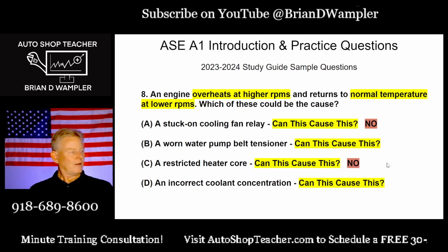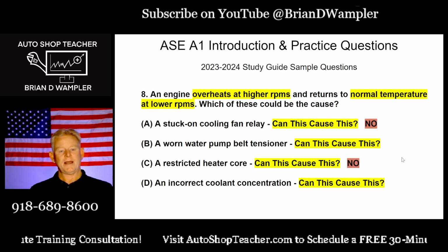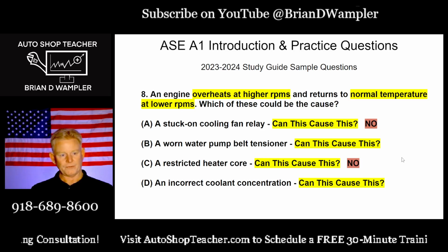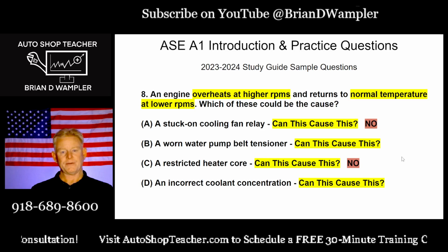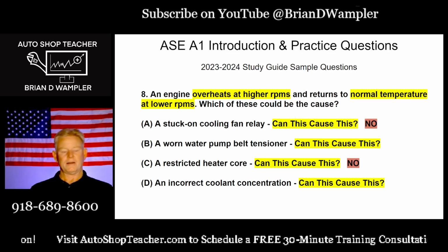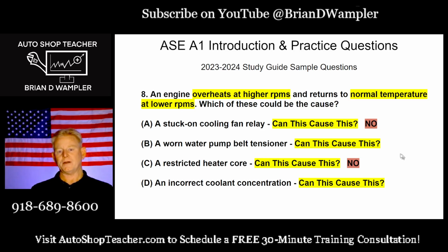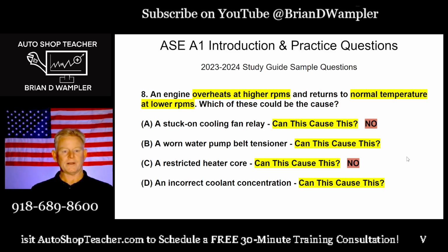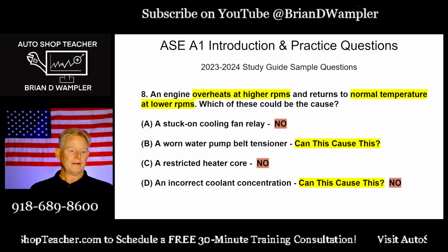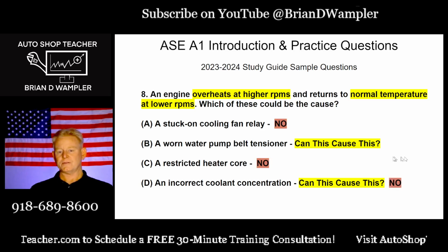Okay? So hopefully you can eliminate A and C right away. Because if the fan was stuck on, definitely is not going to contribute to an overheating problem. And heater core, it's not even a player in this question that we're trying to answer. So, can incorrect coolant concentration cause this?